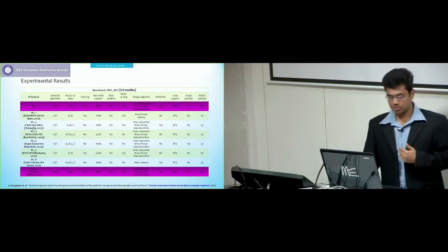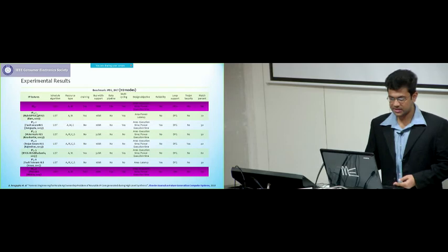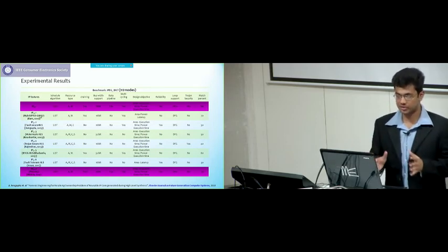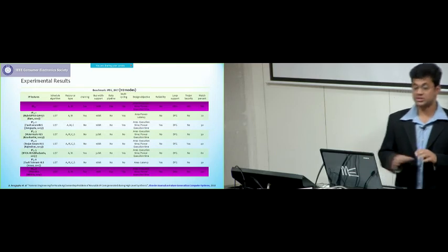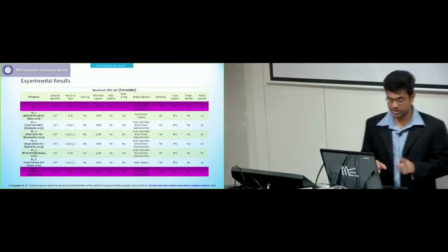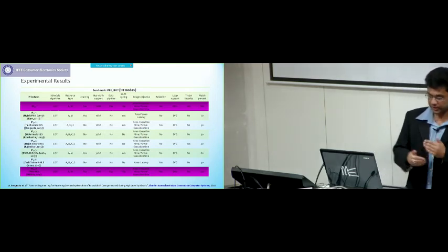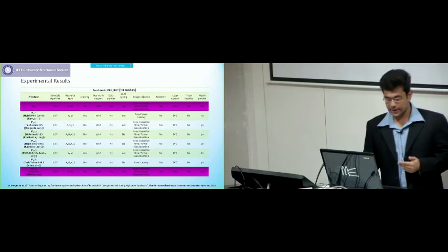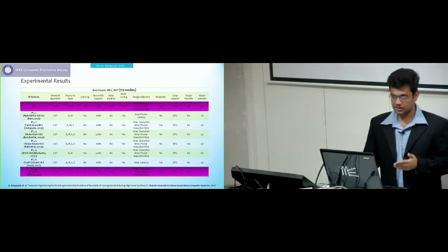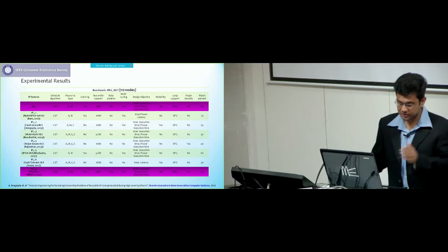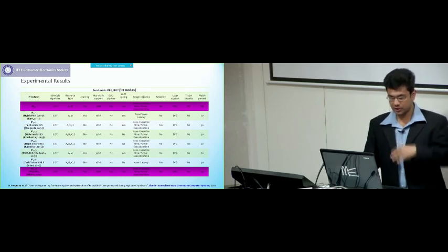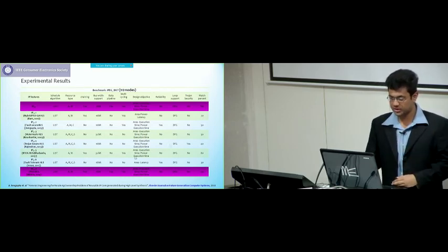And based on these competing tool vendors from IPCT1 till IPCT7, these are the 7 claimant vendors who are trying to get ownership of it, but of course 6 of them are falsely claiming ownership and 1 of them is correct. We have to find out which one it is. So, we generate the HDL codes from each of the HLS tool vendors and apply CFE on that, and this is what we have got, the feature extraction of each of these tools.